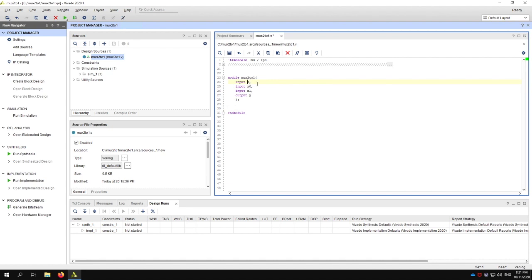Although there are exceptions to this, where you can start a module name with other characters that are not letters, for the purposes of this course, pretty much everything we do will need to start with a letter. You absolutely cannot start it with a number though. Similarly down here, if instead of calling my input x0 I wanted to call it 0x, again I'm going to get that red wavy line that indicates a syntax error.